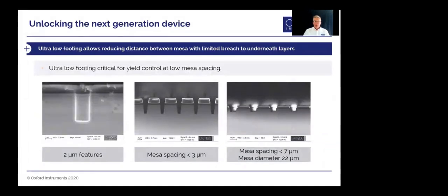Looking towards the next generation of devices, there's some talk about going to more tightly packed VCSELs, which allows you to get more power from a densely packed array, and this also requires new etch processes. So we developed new etch processes to fit the device structure going forward.